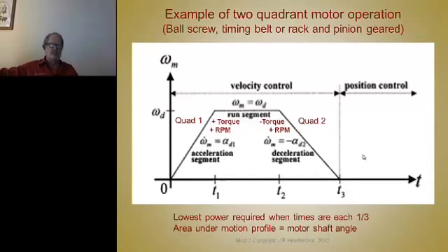It's interesting that diesel locomotives can't do that. When they decelerate or stop a train, the generators connected to the diesel engine generate a lot of power, but they can't put that back. They can't convert that back to diesel fuel. So they have to put big resistor banks on top of the locomotive to convert that energy to heat.